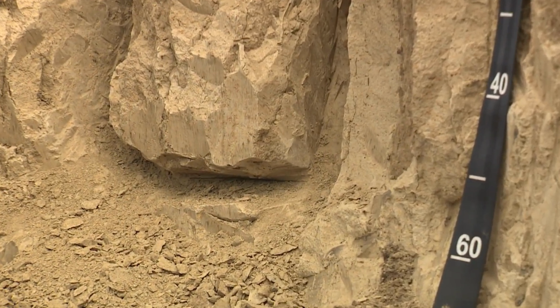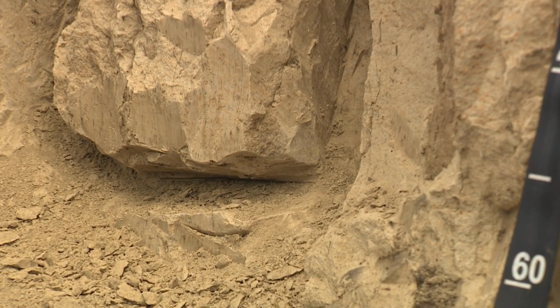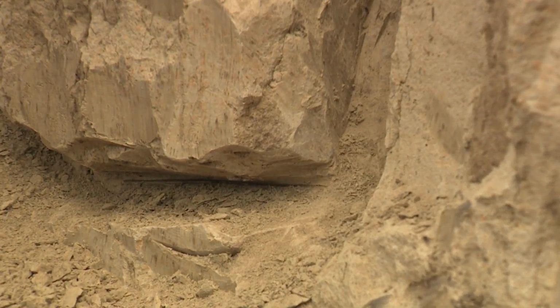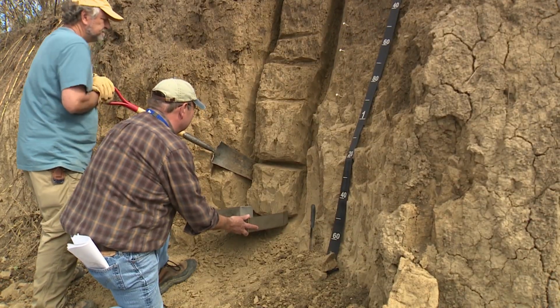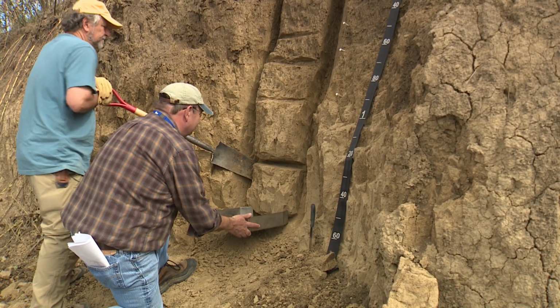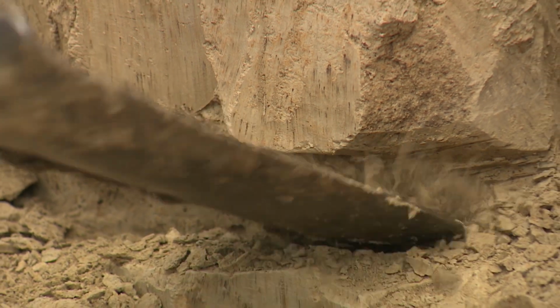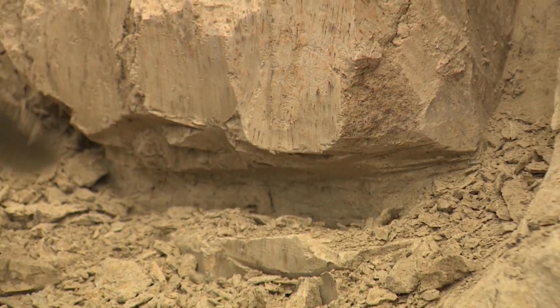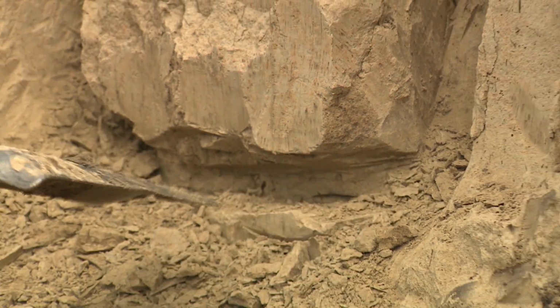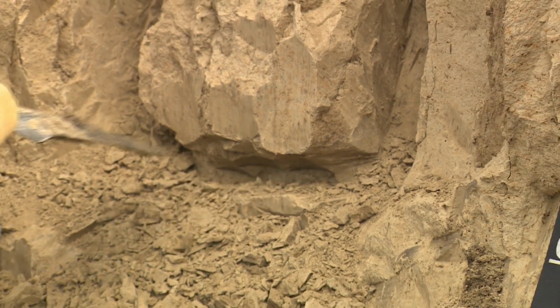It's rather like collecting a soil monolith, and that's been done in advance. We're going to then take these horizon boundary zones and cut those out further. It's very important and helpful, saves you a lot of time and trouble in this process, to sample from the bottom up.